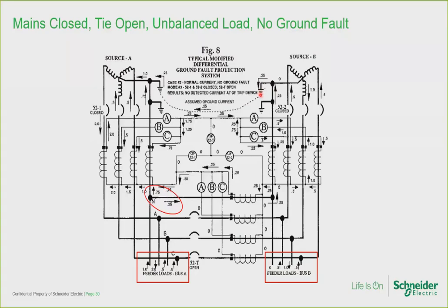Then across the ground bus over to the system bonding jumper of source A, where the 0.25 per unit neutral current rejoins its 0.75 per unit brother electrons and flows to the source A neutral as 1 per unit. The multiple neutral grounds create a parallel path in the switchboard.